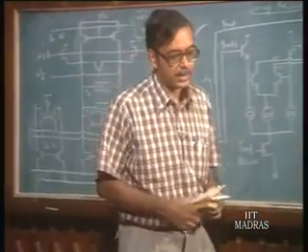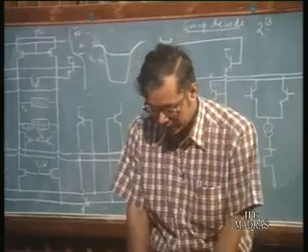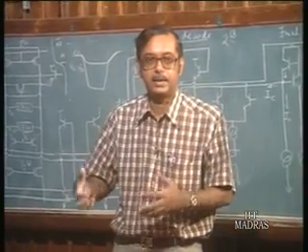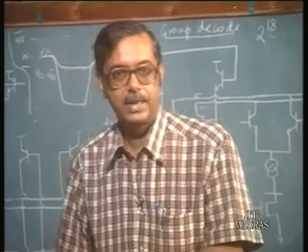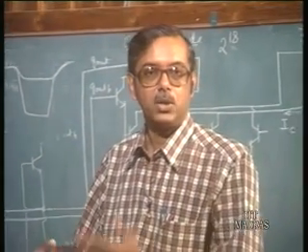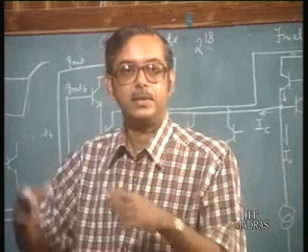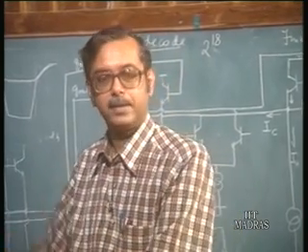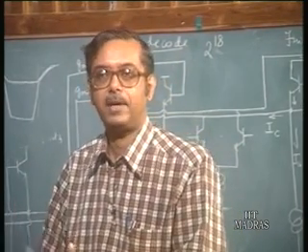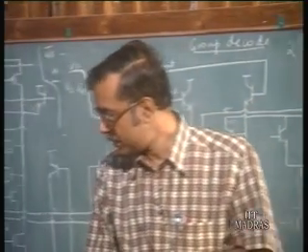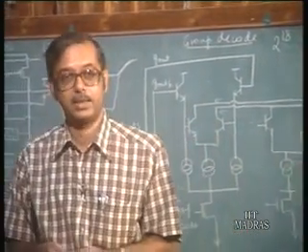So, this is the circuit of a BiCMOS static RAM, and as I said, the BiCMOS static RAM is going to be much faster than CMOS static RAM because of these properties. Only a small difference voltage on the data lines is necessary, and we are using a bipolar sense amplifier to sense this small voltage. So that brings us to the conclusion of this section on static RAMs.